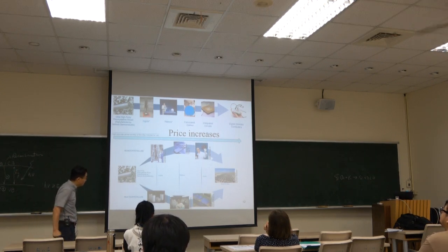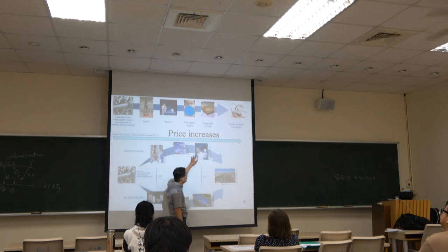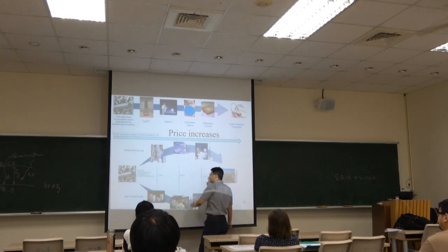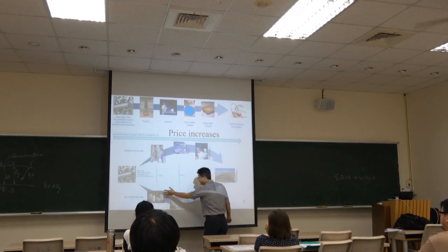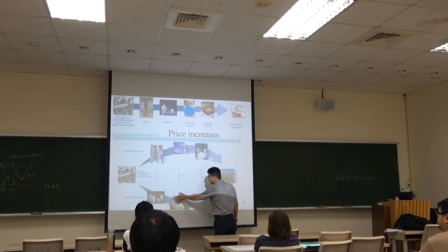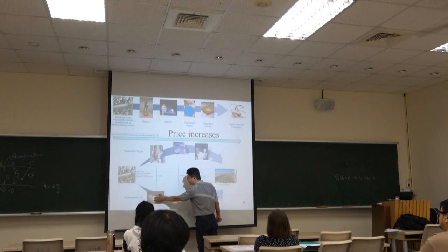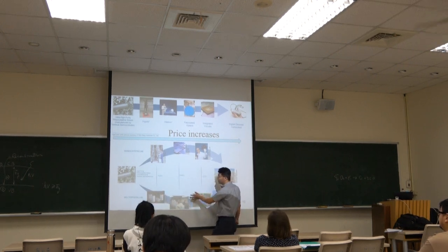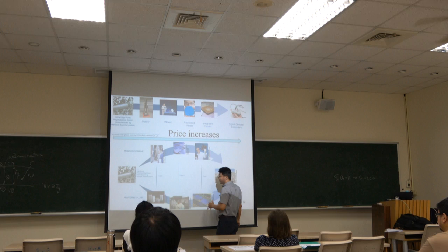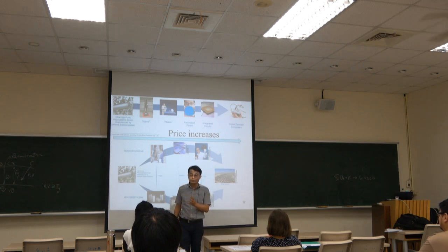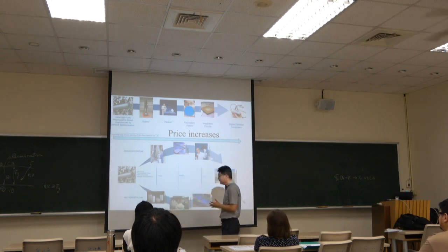For example, the single crystal manufacturing process, later we will show about it. Polycrystal is still one of the very famous processes for the manufacturing company. They would like to use the polycrystal because polycrystal is much cheaper than single crystal. And then the important case is how to purify the grain boundary area, the metal transition in the grain boundary area. This is very important.